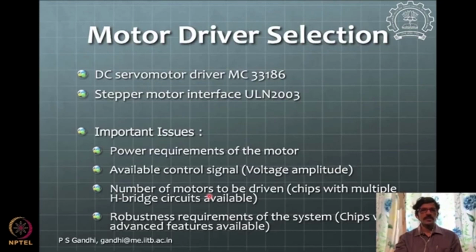Then there are many different kinds of drivers that can be possible for this H-bridge, depending upon the kind of motor. So a permanent magnet DC motor can be driven by the H-bridge, or a stepper motor can be driven by a simple ULN transistor amplifier.